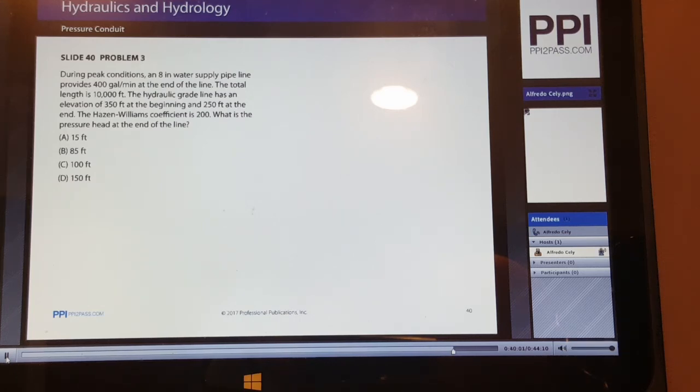This problem is another application of Bernoulli's equation. The intent of the problem is to show how to use friction losses when calculating the energy at different points in the system. Please note that both the energy grade line and the hydraulic grade line can be used on this type of problem to graphically picture what is going on.